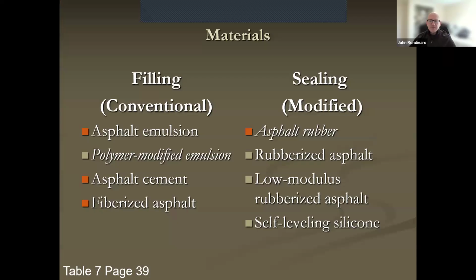This is definitely not a candidate for any sort of crack treatment. You really got to be doing something heavier at this point. The difference in materials when you're talking about filling and sealing: filling is a conventional material, a material that hasn't had any kind of additives or modifiers included with it.